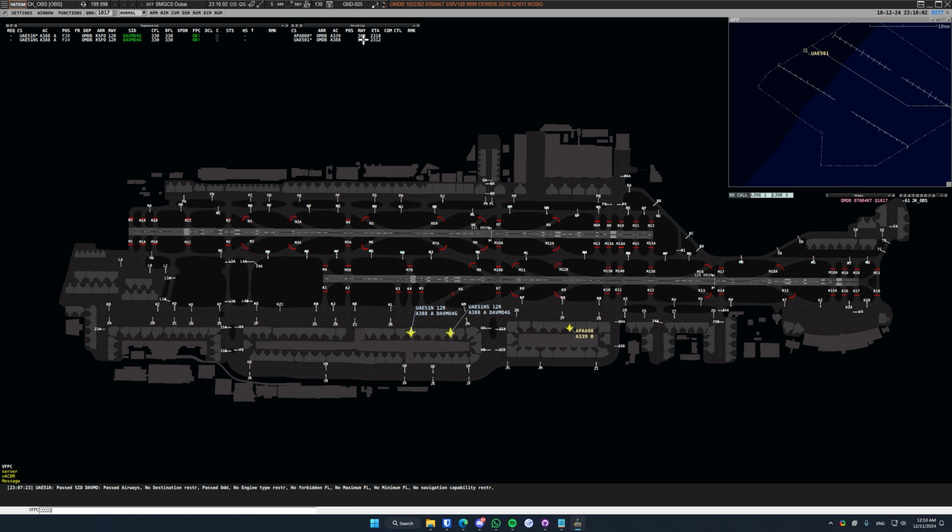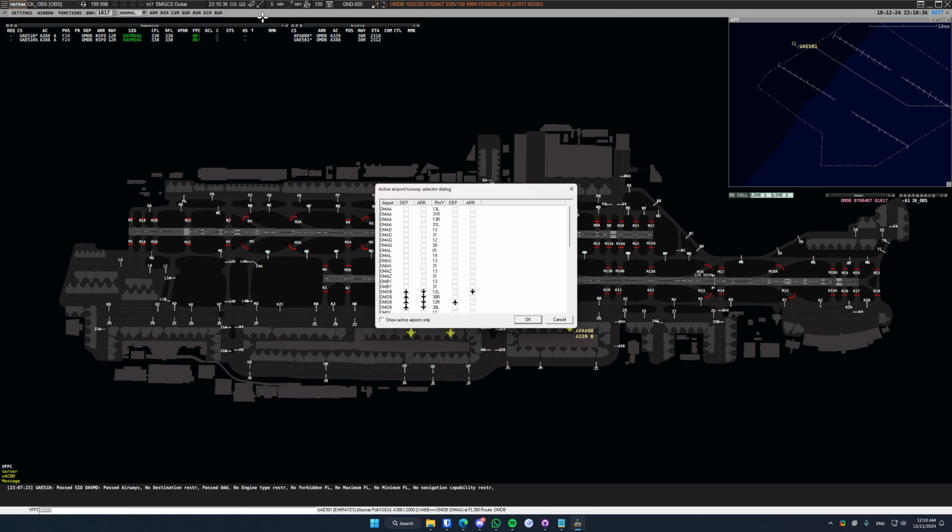To the right of that, you have the runway for arrival that's been set by the controller or assigned, and then you have the ETA, the estimated time of arrival. Again, you have the communications area, which will tell you if the pilot is able to transmit, receive, just receive, or go via text. The clear to land flag, which is used only for controllers rated approach and above, and the remarks. Remember that this will only show if you have set your active runways in the active runway dialog.